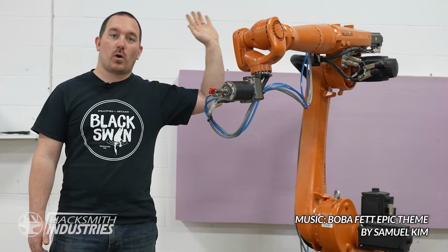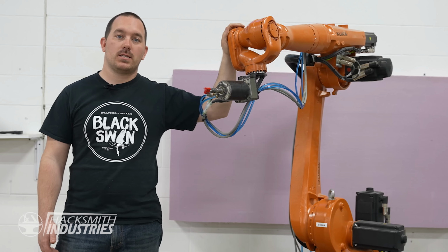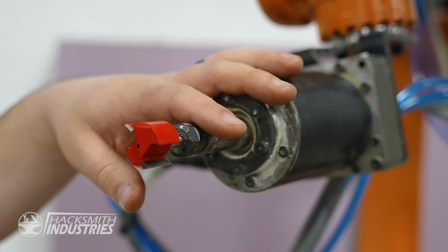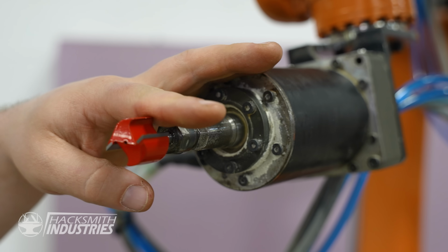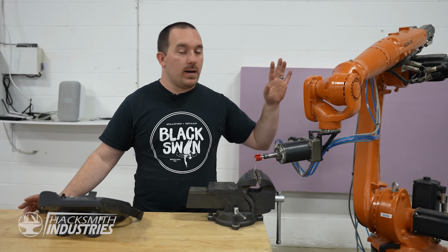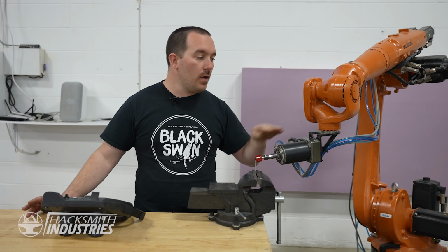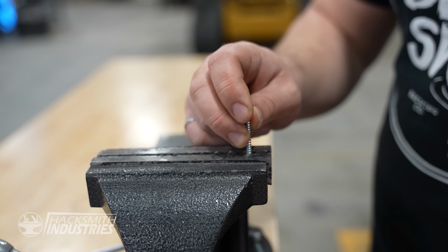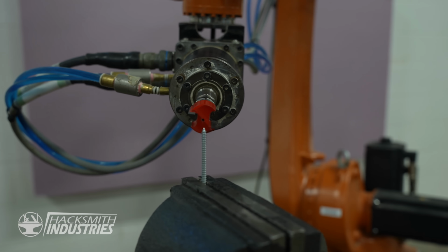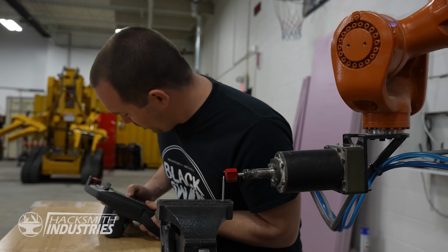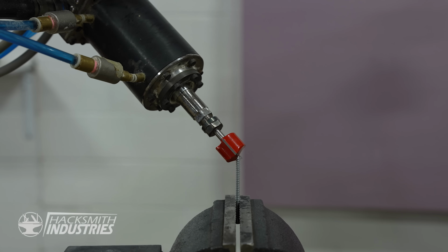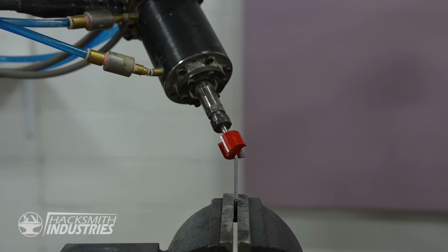To cut out this foam, we're going to be using a KR20 from Kuka Robotics, as well as a liquid-cooled spindle from PushCorp. This spindle just has a wood routing bit in it that it spins at 20,000 RPM to be able to cut out the foam. The first thing we need to do is tell the robot where this tool is on the end of the arm. The easiest way to do that is just get a point out in space and have the robot touch the tool to that point at 4 different angles. If it knows all the positions that it used to put the tip in the same spot, it could figure out exactly where it is on the end of the arm.